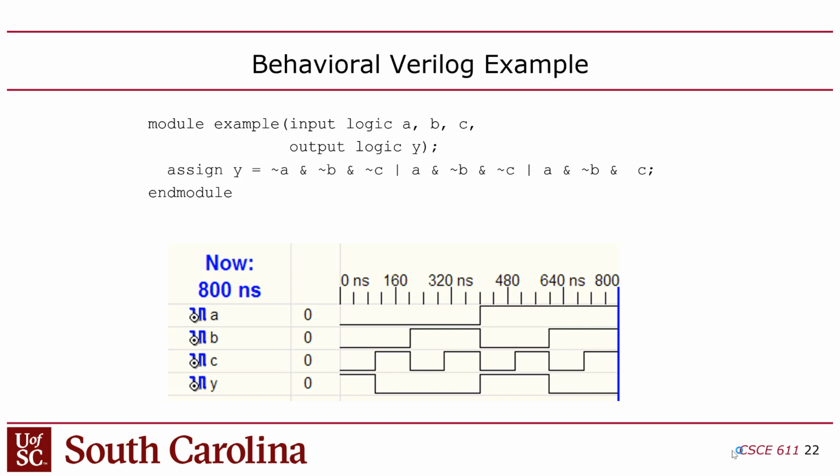But notice there's no delay there. The change in input and the corresponding change in the output happen instantly. Now, in reality, that's not instant. There's a propagation delay because these circuits are capacitor and resistor networks. So it takes time to charge and discharge the capacitances in a digital logic design. And so in reality, you would see a delay between C changing and Y.